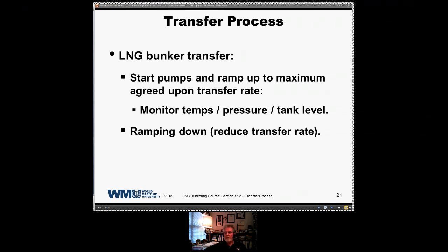The system is being constantly checked by ship's personnel. We have crew members who will be out observing the transfer system as we begin the cargo transfer. We continue starting pumps in sequential order, usually over a period of anywhere from 3 to 6 minutes between each pump start.